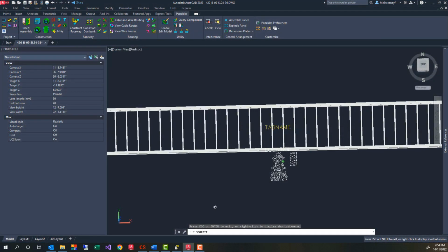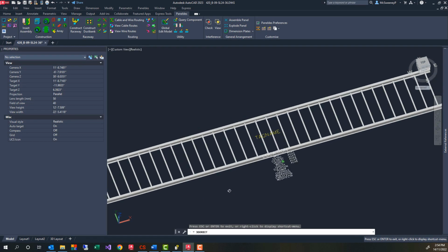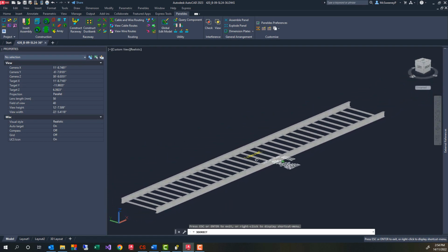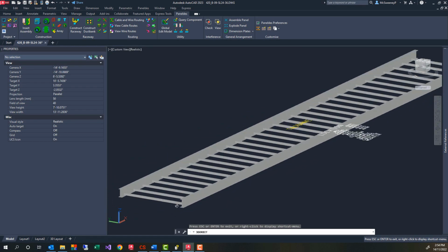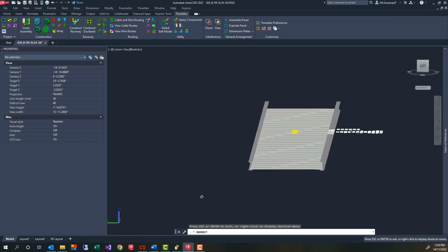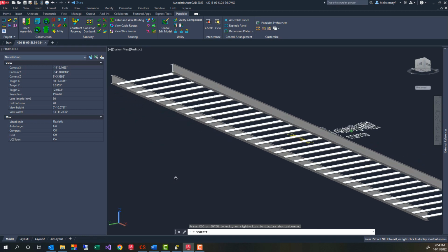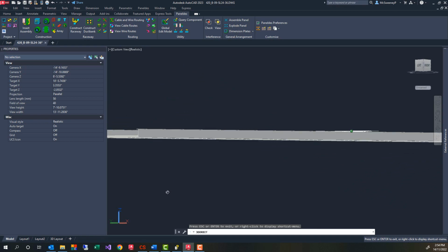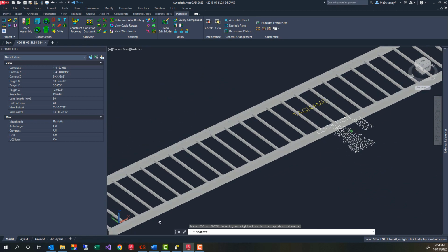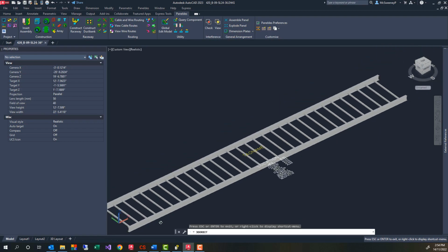Paneldes components can be modelled as 3D blocks, containing solids and, of course, attributes for tags and specifications. The system is efficient and provides a realistic model. The block I am displaying is a cable ladder. You will note that the ladder does not contain extreme detail. Extreme detail will slow down a CAD engine. You can easily make your own component blocks.